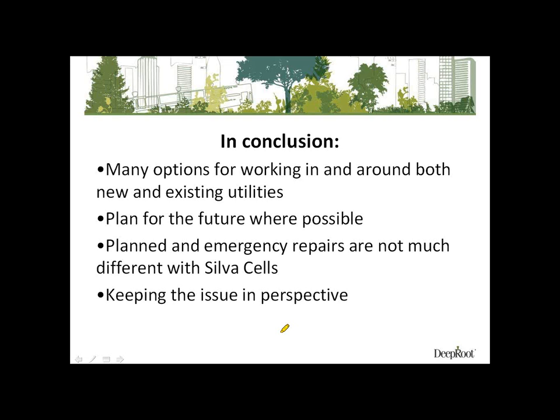Okay. We get a lot of questions about the aggregate subbase that the Silva cells sit on, that 4 inches or 100 millimeters. Typically what we like to see there is a road-base type product, a 1 inch or 3/4 minus with some fines, because it's nice to have something to grade out smooth on top. So you get the base to sit level and you get a full contact area of the base with that surface.